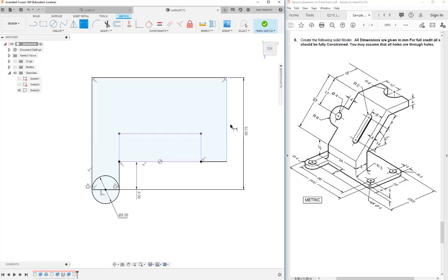Okay, and so now the only thing, I can't drag this up anymore. The only thing that's unconstrained is this edge. It can still go away. But everything else seems to be constrained back to my origin. So looking around for those dimensions, I could also use that reference dimension if I don't see anything that I could use.